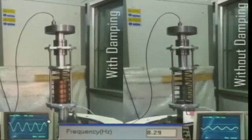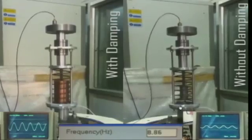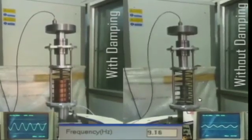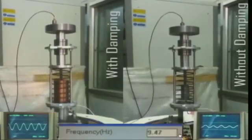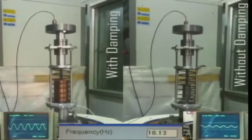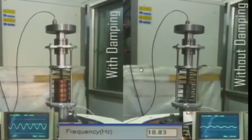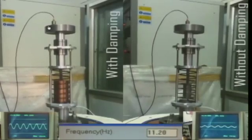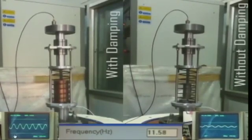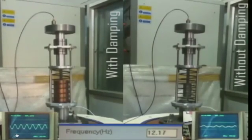around 8 Hz. So, it is between 7 to 8 hertz level you would see it. As you increase the frequency, you may come across a situation where this will be even more vigorous here. On the other hand, you will see that with the damper there will be hardly any, as I told you that the damping is very important close to the resonance. So, whenever you come across the resonance, you will see a sudden decrease in the whole system. So, that is kind of an example of how a system would behave with and without damping.